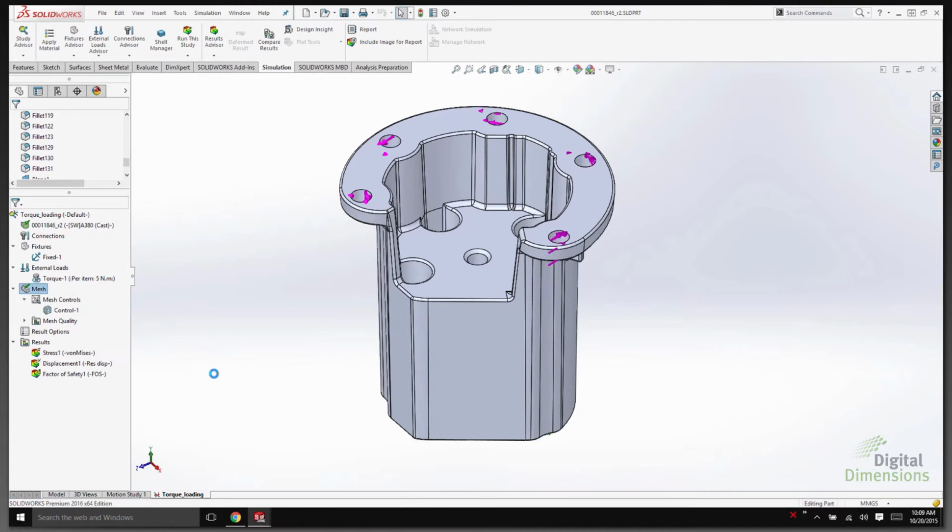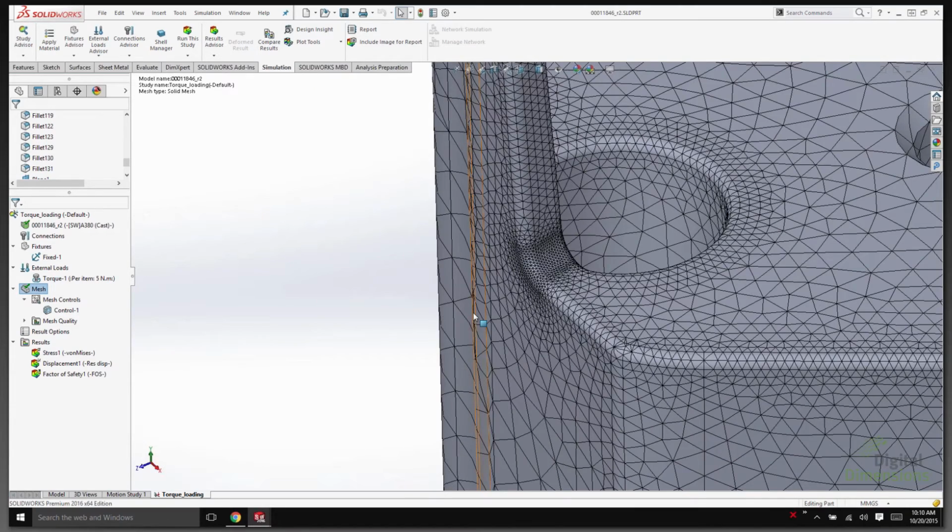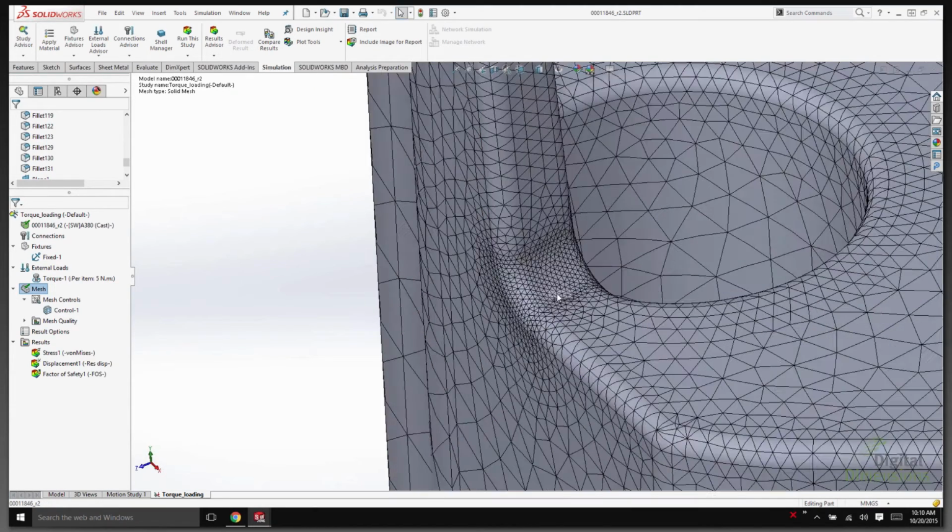And this is where a lot of us, sometimes there's a lot of confusion, right? As we try and understand the mesh quality, what's happening with the mesh internal to the model, sometimes we just have to make assumptions. New in SOLIDWORKS 2016, we now have a way of evaluating the mesh with the new mesh sectioning. So if I'm curious about this region as it is, and want to see what the mesh is looking like 3-dimensionally as it moves into the depth of the object, I now have a new option for evaluating that mesh. So under this mesh quality plot, if I right-click on it, we'll go ahead and show the mesh quality plot, and I can right-click on it, and there'll be an option now for mesh sectioning.